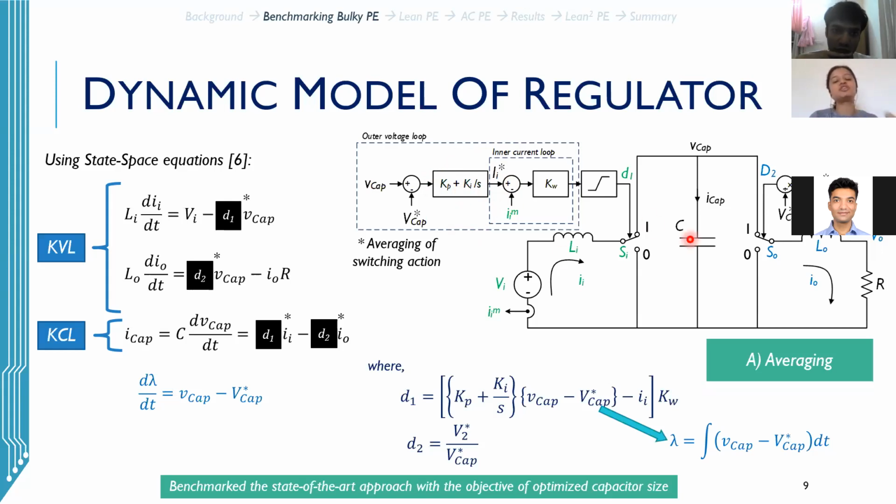So we are just trying to map how, if we reduce the value of the capacitor, there is a risk of this system going unstable, and how we can make sure that in lower capacitance systems, the system remains stable. So the capacitance value is the variable in this case. Right, the capacitance value. Yes.